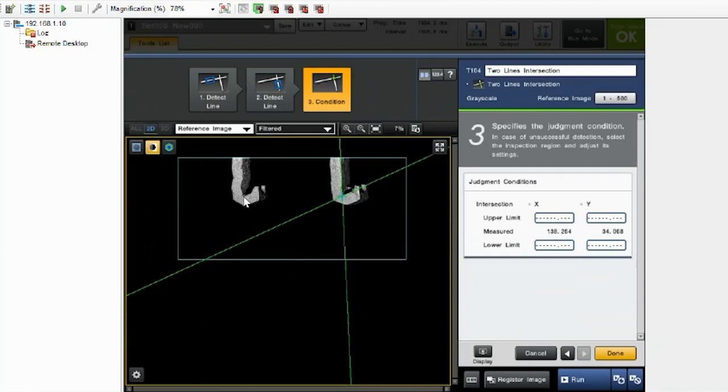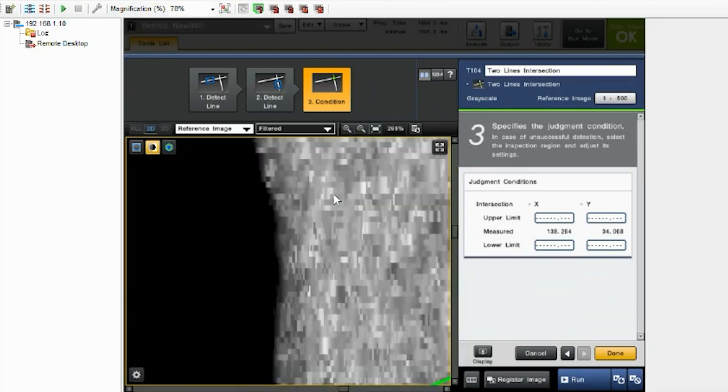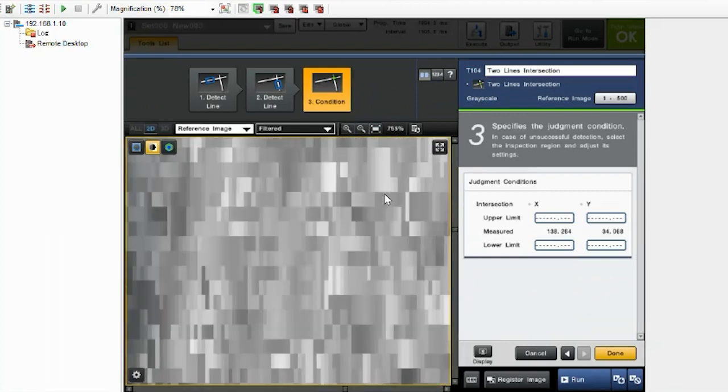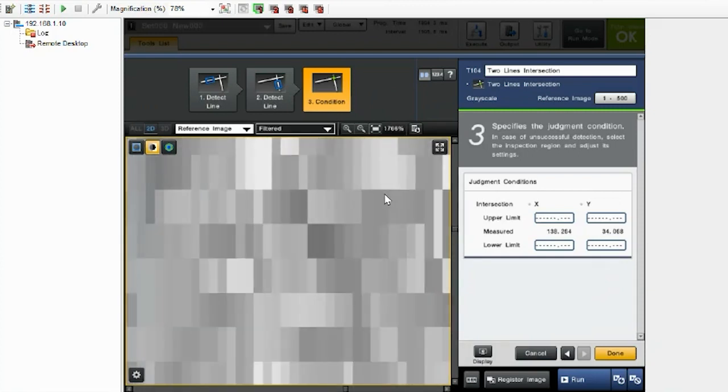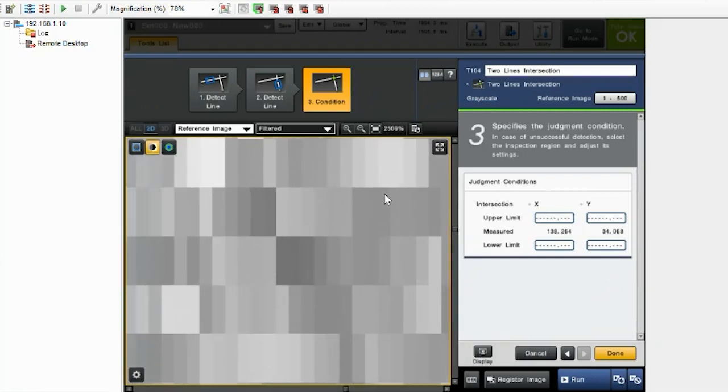If you recall, in the settings we changed the 0.025 to 0.030. What that was was our pixel pitch. Go ahead and zoom in to the hook all the way, as far as you can. So the pixel size from left to right, each pixel size is 0.03 millimeters.